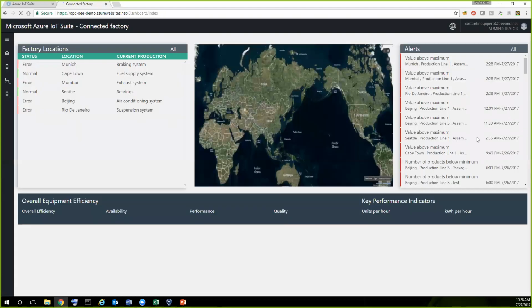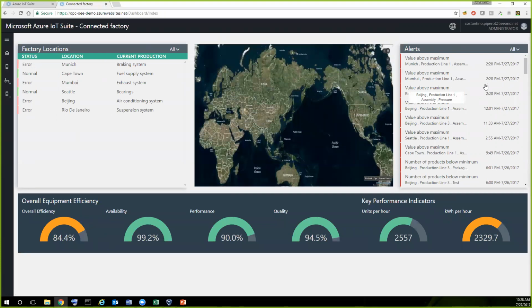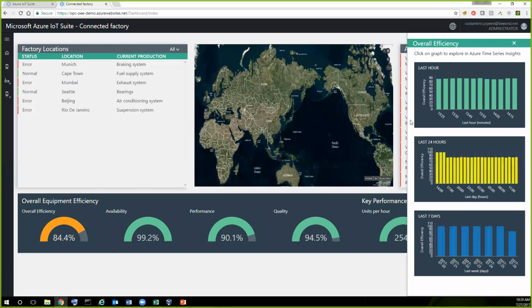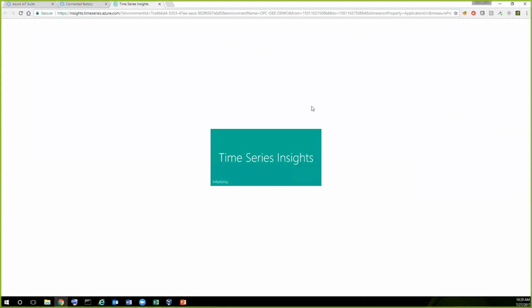So why is that relevant, the fact that we choose OPC UA? Because OPC UA doesn't just transfer data. It also transfers the semantics of that information model. If I'm looking at these parameters, for example, an OEE calculation, well, those calculations are based on factors that need to be aggregated: availability, performance, and quality.